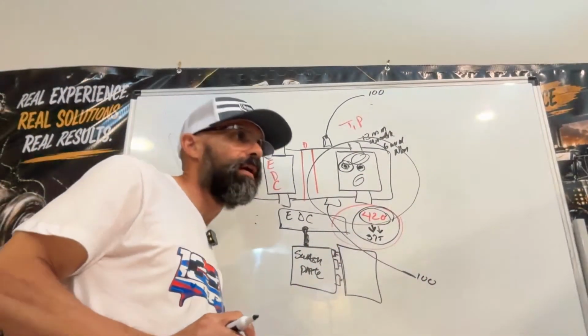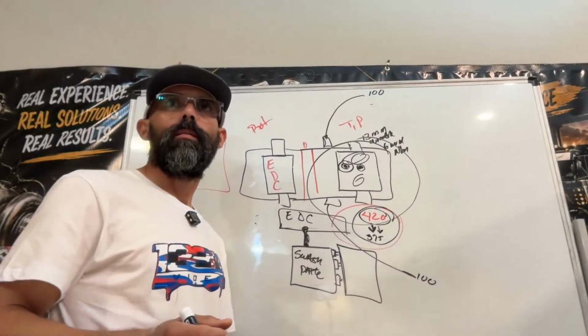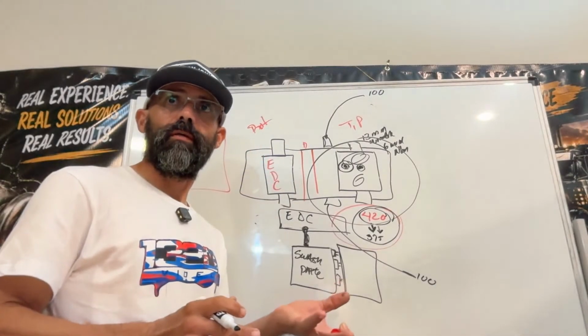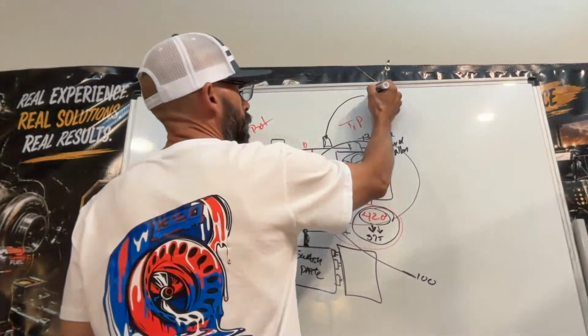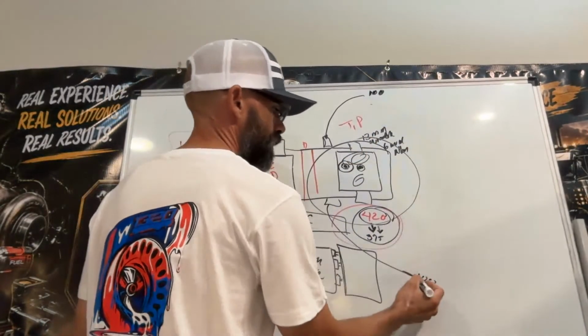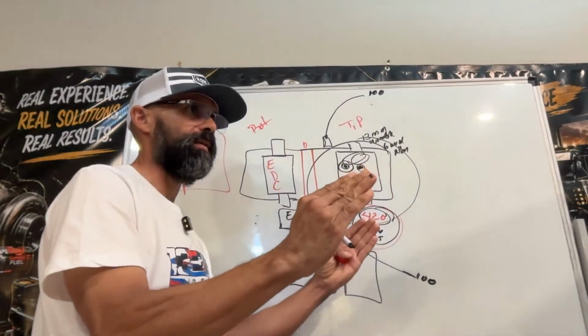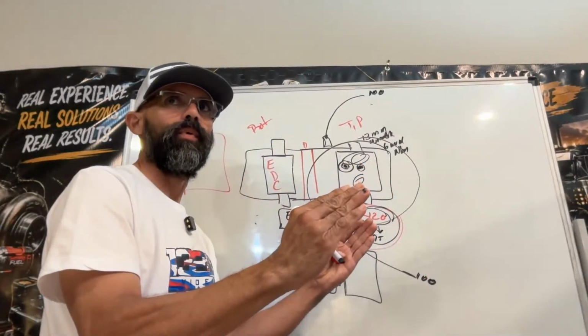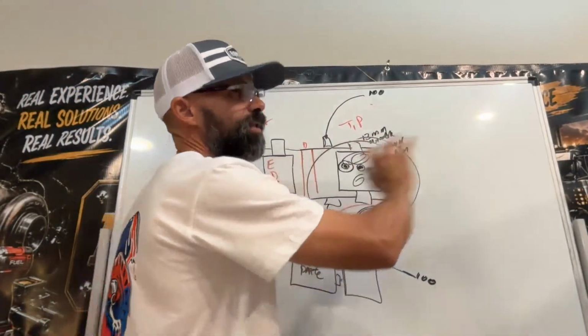Some people are like, no, I can do it by eye. Well, the carriage is not moving anymore. But if you want to do it professionally and accurately, two gauges. Keep an eye on this one and keep an eye on this one. Once you see that both gauges equalize, giving you the right pressure, that's it. And you're going to see that your carriage is not going to move anymore.